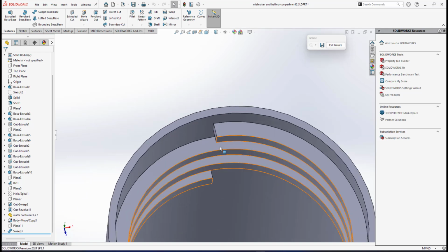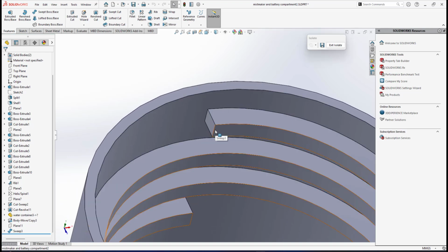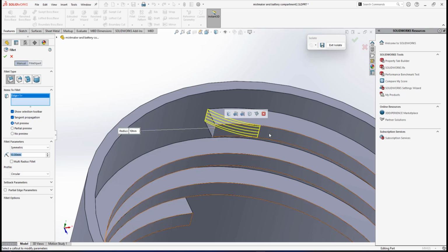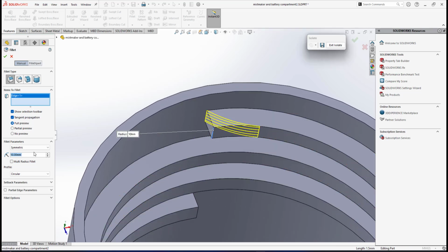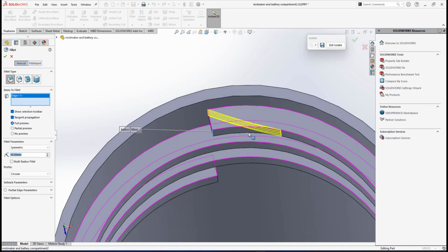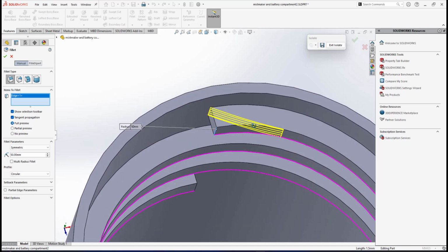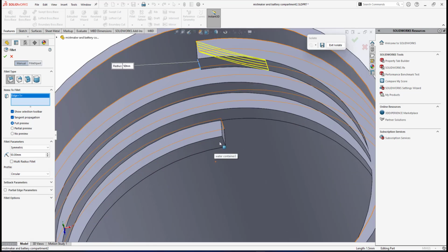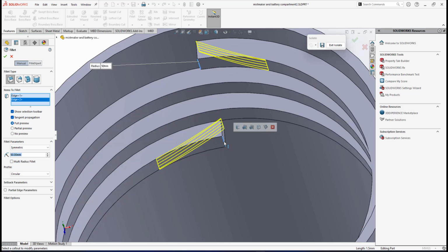So what I will do, I give a fillet radius. Let me try a fillet radius at these edges. I will try a fillet radius of 10, just to check. If I make it a little bit bigger, about 20. Let's try 50. I just try and error to find the maximum radius that it can go. Okay, I think 50 is good enough. So this one will be 50, and also the bottom, these edges will also be 50. It's easy to slide in.